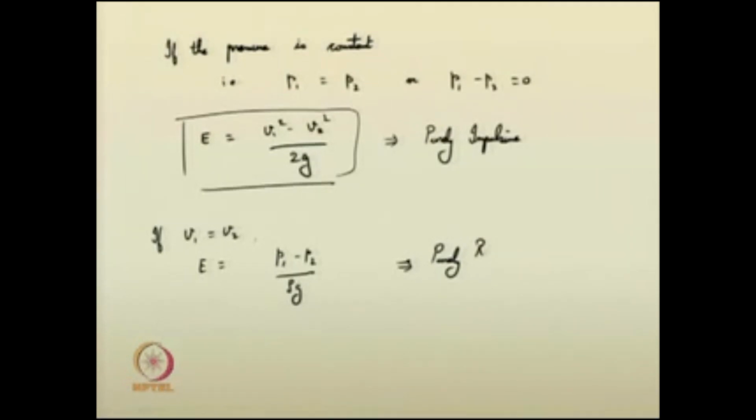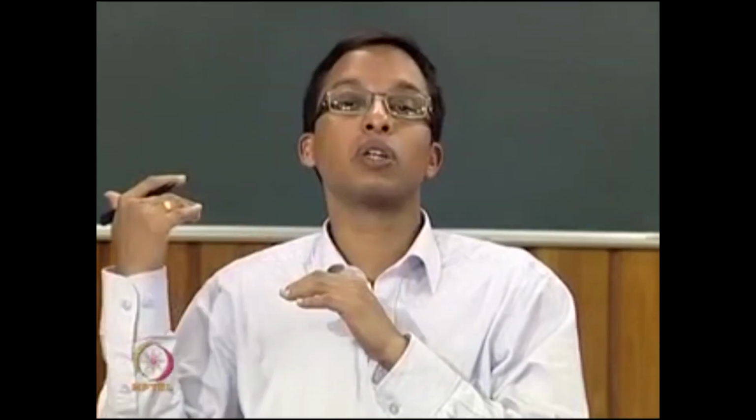Such turbines are purely reactive turbines. In the actual case, your turbine may not be purely impulsive or purely reactive. You can find some degree of reaction in turbines. Based on that, if the degree of reaction is quite high, it comes under the category of reaction turbines. If the degree of reaction is very less, it can come under the category of impulse turbines.